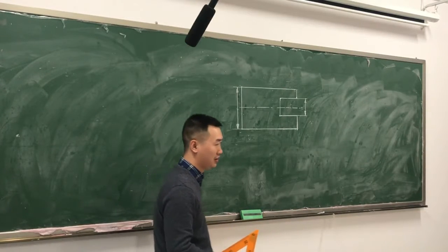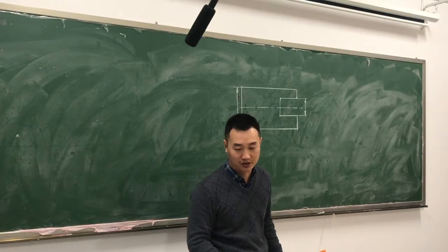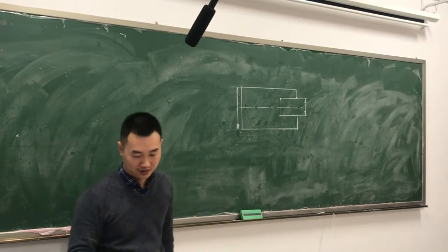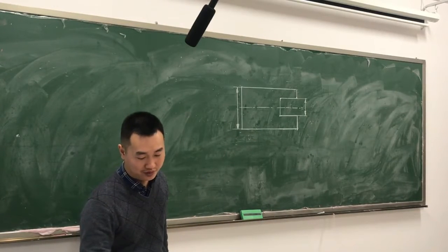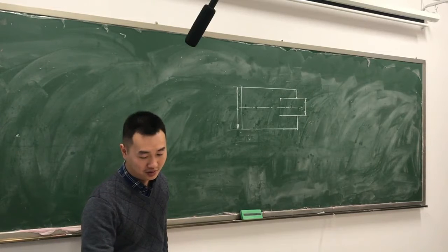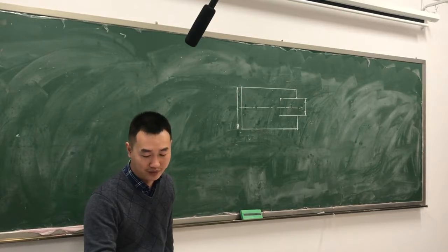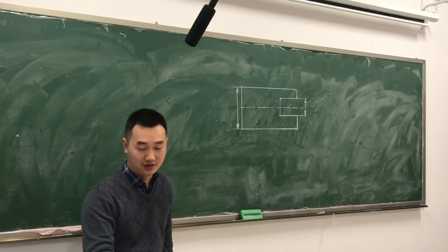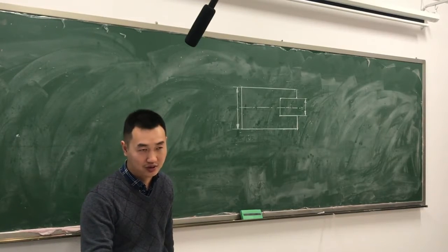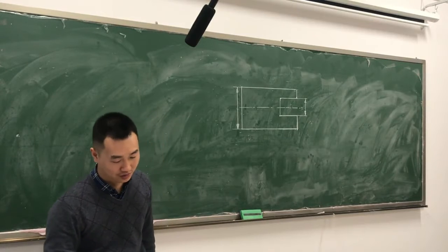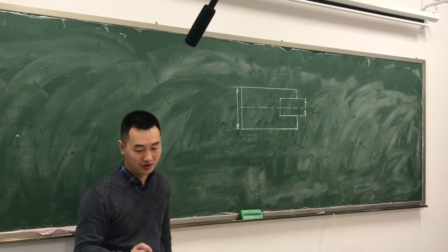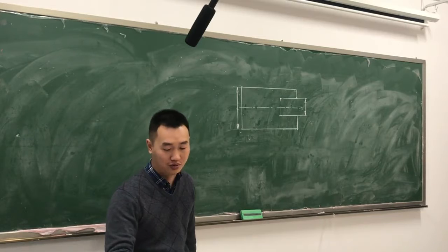So where is the median plane of the workpiece? Derek and Chen Gong labeled the flatness of the upper face. In fact, the upper face does have the flatness tolerance. But here, both of you made a little mistake. You didn't point to the median plane.